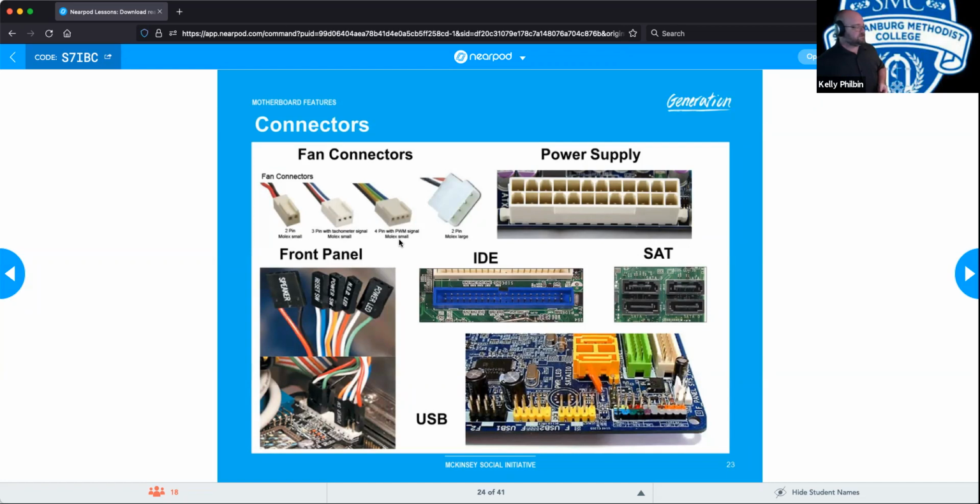Up here, we have a 4-pin fan connector. Typically you would have your negative post, and then one pin for turning the fan off and on. And then you would have an extra pin that tells the fan what speed to run, like how fast the fan is going to turn. So in a 4-pin fan connector, that's what you would see.